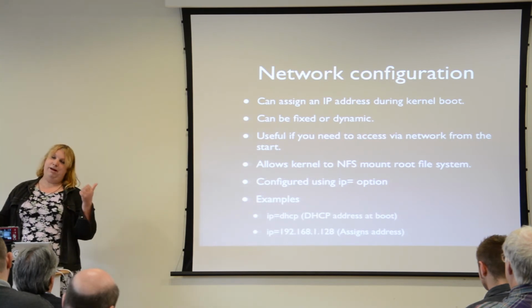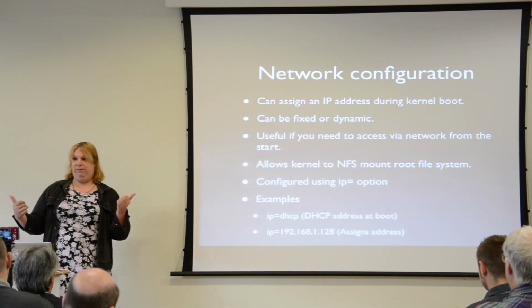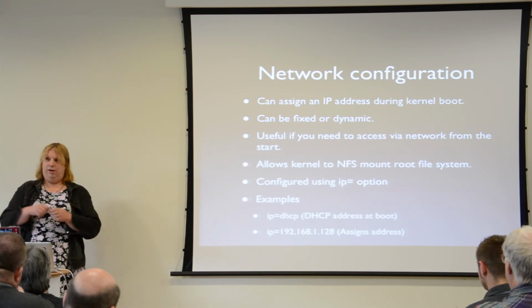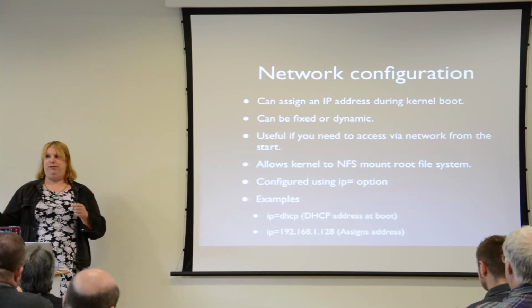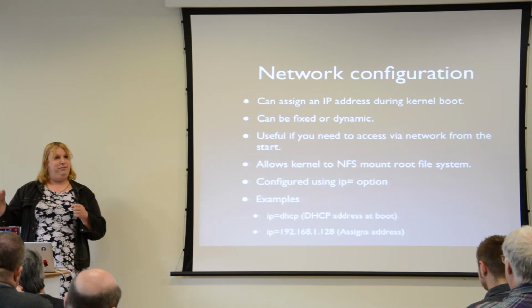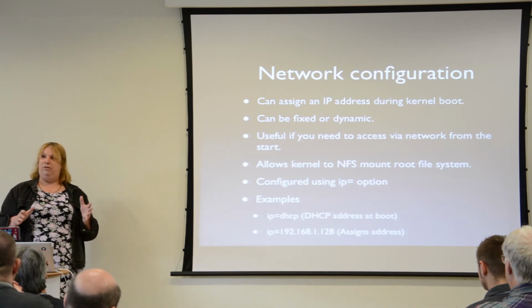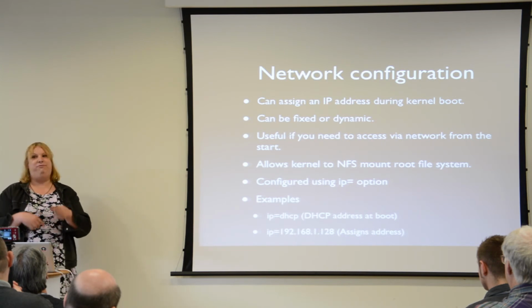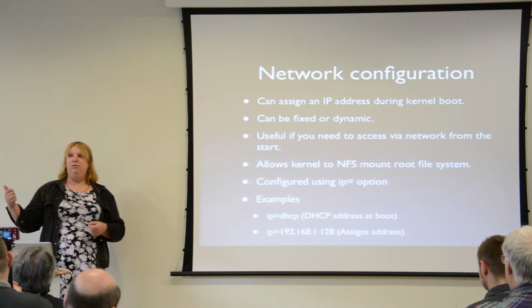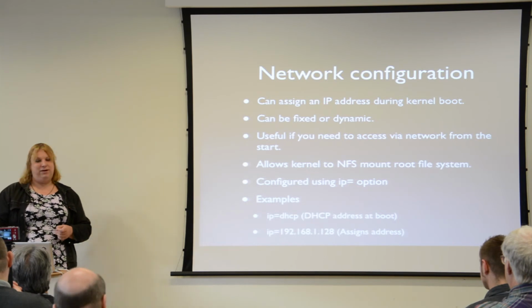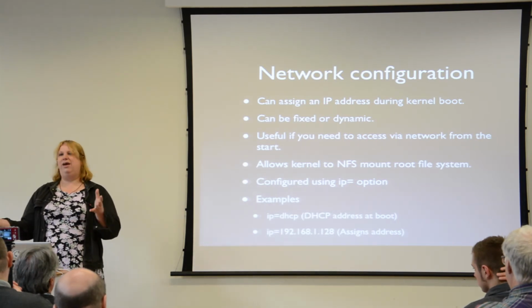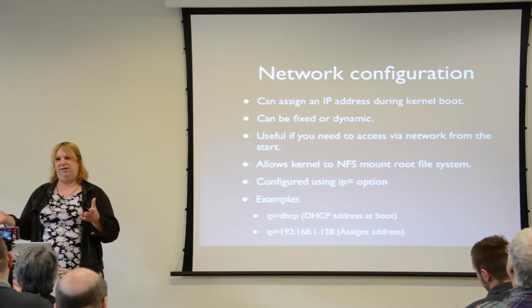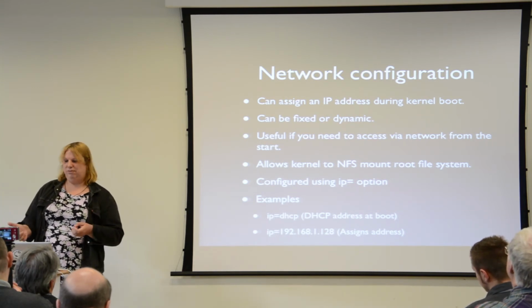So if we remember going back to CFE and U-Boot and the fact that we could TFTP in a kernel and run it, the kernel's pulled off our machine from the TFTP server, that runs up, and then it mounts the file system that's also on our system, which means that we've got full control over it, easy to rebuild, we don't have to reflash or anything like that. And the only thing stored in the device is the bootloader. Okay, there's a time issue, so sometimes you don't want to do it, because NFS is not as fast as using a local file system.